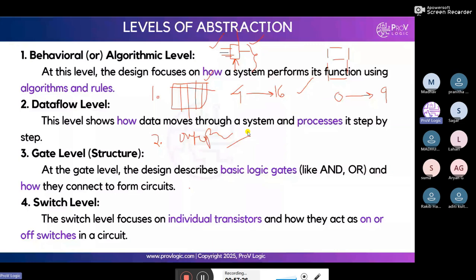So how will you draw the circuit diagram in a gate level netlist? By using the basic gates and universal logic gates, you will draw the gate level netlist. The fourth step is converting the basic gates into CMOS. So the gate level netlist is converted into CMOS transistors. This is how we draw the digital circuit, and finally we get the gate level circuit.